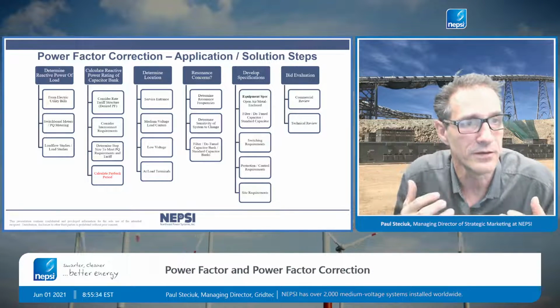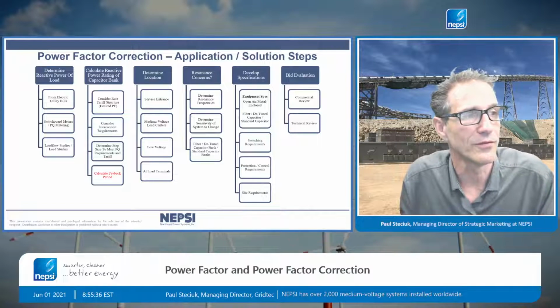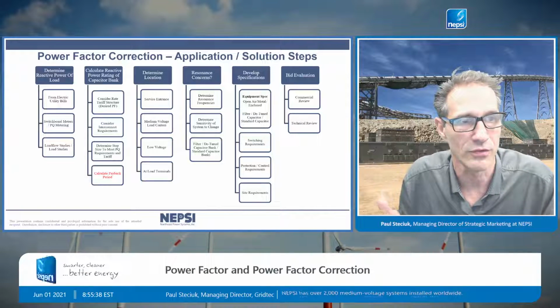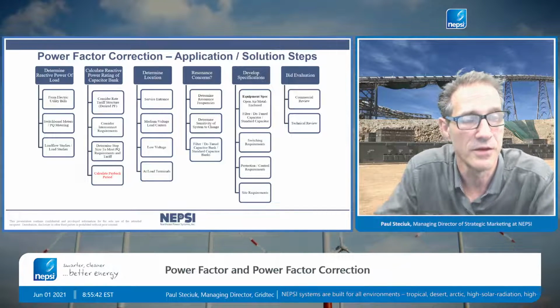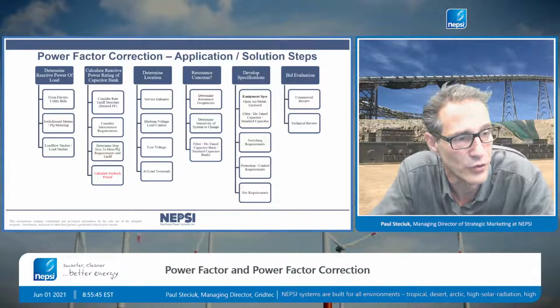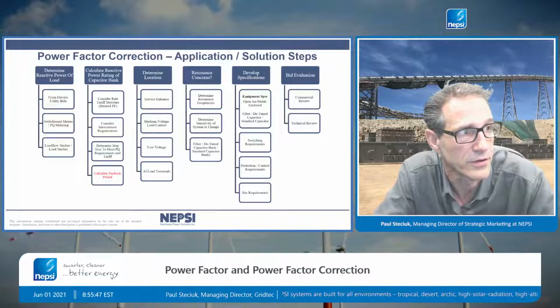In my opinion, whether it's a detuned cap bank or a filter bank, they're all the same thing. It's a capacitor bank tuned to a frequency. So my way of thinking is, a tuned bank is a filter bank, period.